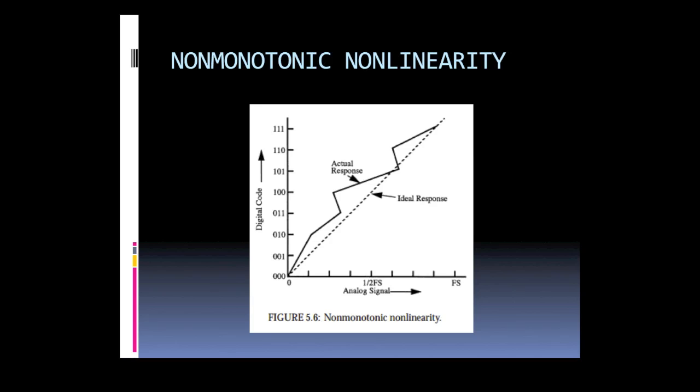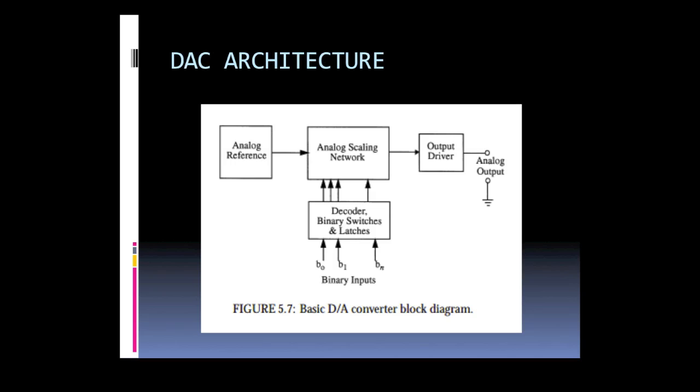Post-fabrication trimming techniques can be used, but at the expense of added cost and complexity to the manufacturing process. Various architectures can be used to allow high-speed or high-accuracy data conversion. To reiterate, a digital-to-analog converter, also known as a DAC, decodes a digital word into a discrete analog level which can either be current or voltage-based, depending on the application.